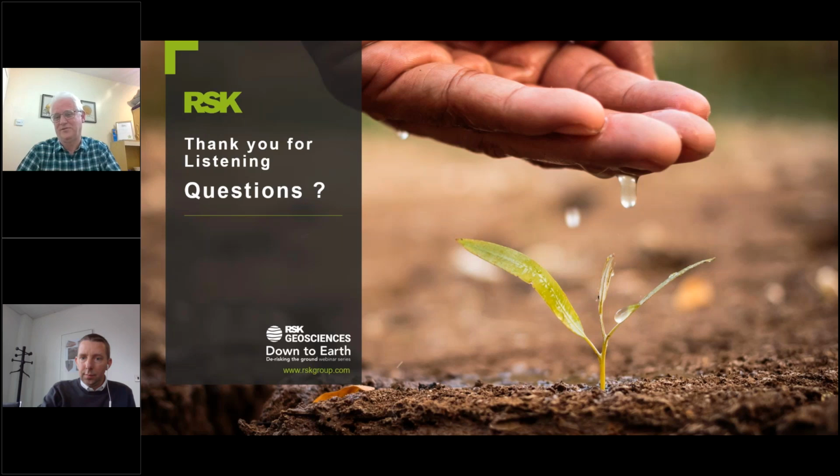The geology of the UK would lend itself to the fact that the soils in the southeast are definitely the ones that are the highly shrinkable illite, montmorillonite rich clays, whereas the soils in the northern parts of the country are predominantly kaolinite rich. So the low shrinkability in the north and probably quite a high sand and granular content. So in the southeast of the country, you will be getting, like that diagram showed at the beginning with the 2070 diagram, roughly 50% increase in the area. And so I think the quick answer is probably yes.